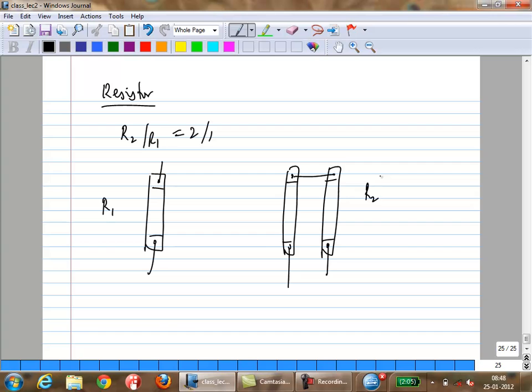So what is the basic idea? If you take a resistor, for example, there are also other systematic mismatch components, and in general, for transistors, anything. You could have, for example, your process which is actually depositing your resistor. If it's, let's say, a diffusion resistor or something like that, you could have a temperature gradient, right? This resistor could be in one spot. This resistor could be at some distance away. There could be a temperature gradient. So the deposition rate, all those things, the process parameters will change.